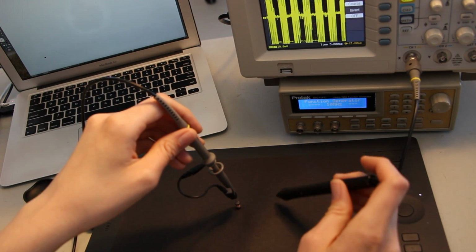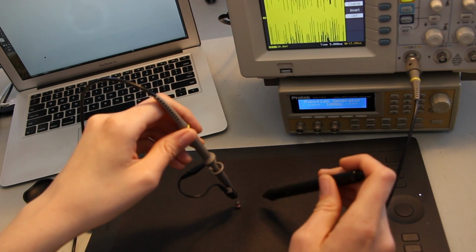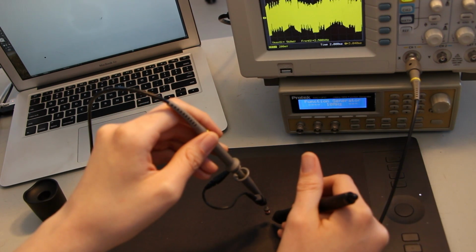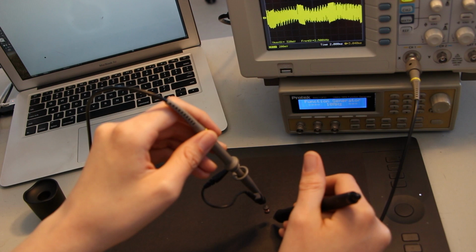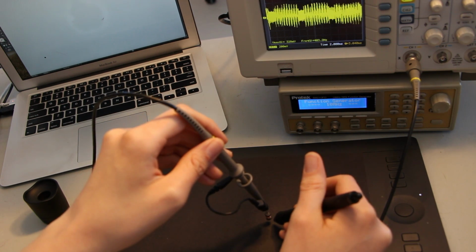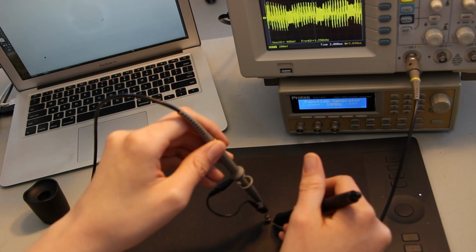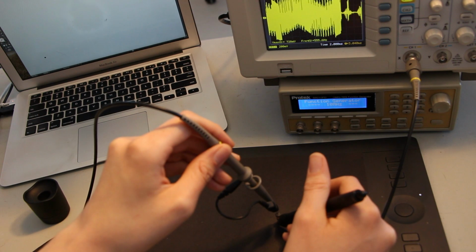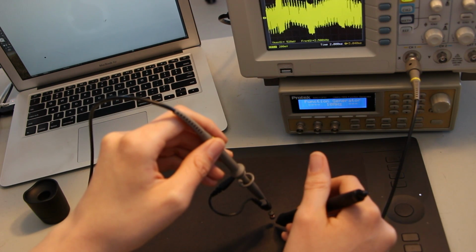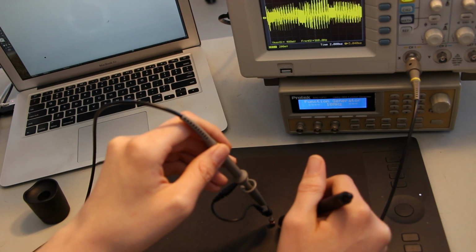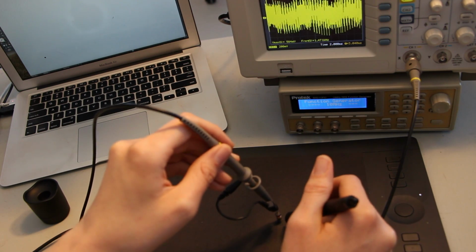If I bring the pen into range of both the tablet and this receiver coil, things get a lot more complicated. There's so much going on that it's hard to see on the scope, but it looks like what's happening is a form of time division multiplexing, where the tablet spends some of the time sending this signal that powers the pen and gives it location info, and then the pen spends some of the time sending back a response packet, which presumably would have information from its sensors as well as information about the decoded location.